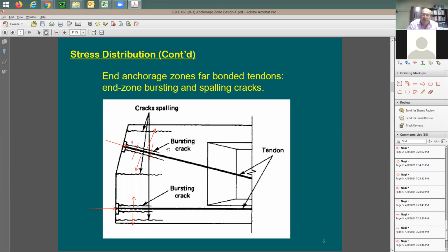So the problem is, if you have any cracks here, this anchor is going to start to move in, which means this block, this anchor, if this starts to crack, it's going to move slightly in this direction. It's going to be a very small distance, maybe you cannot see it with your eyes. But the problem of moving this block in this direction is that you're losing the pre-stressing.